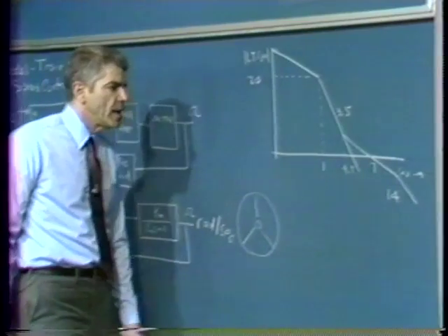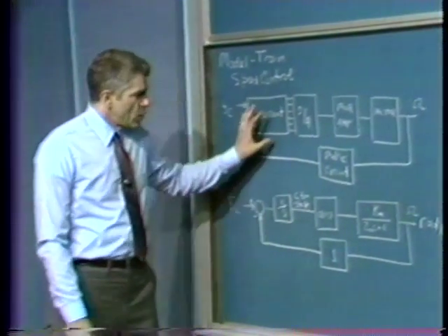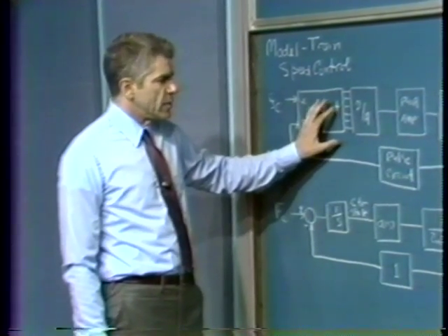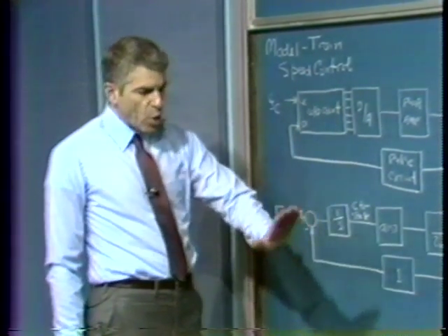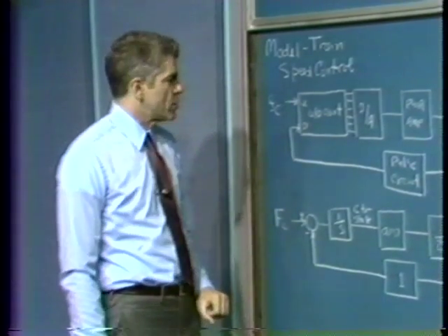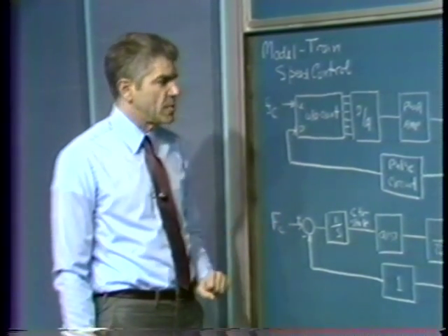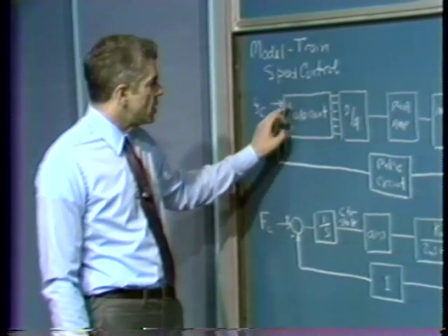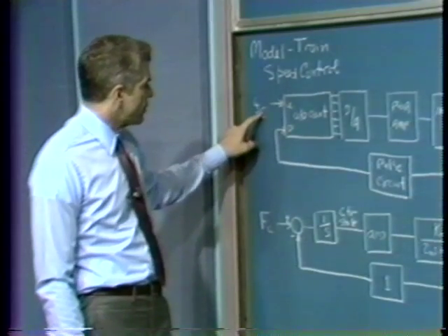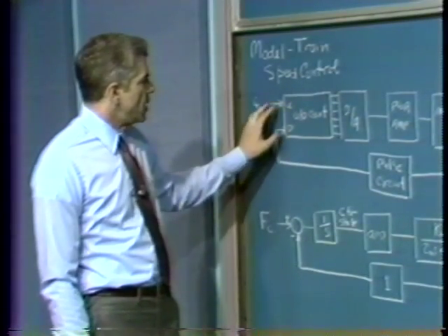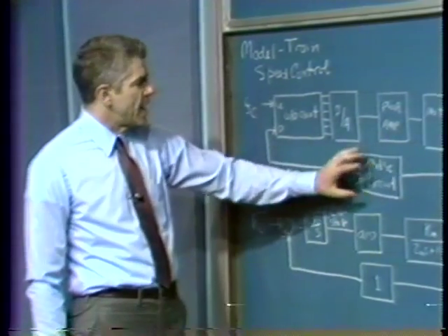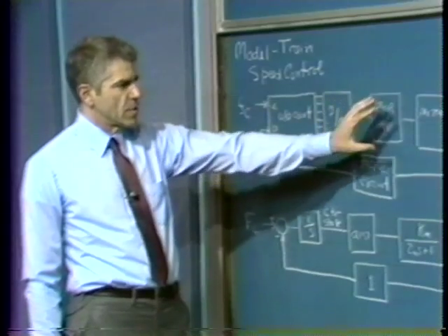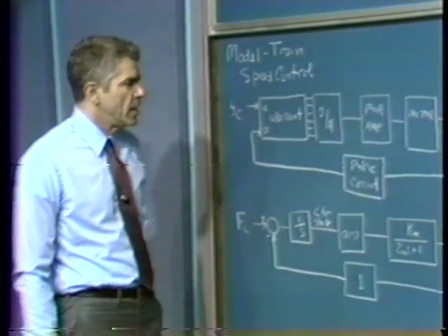Of course, consider how the system operates when we have an increased load on the motor. When the engine has just turned the corner and is going uphill, we find that the motor tends to slow down a little bit. Consequently, we accumulate additional up counts. The reference frequency doesn't change. The command frequency doesn't change. The motor slows down a little bit. We increment the net count in the up-down counter. That gets converted and applies a higher voltage to the motor.